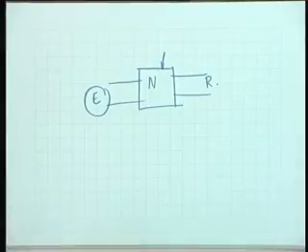You characterize each component by Ohm's law, and then write KVL or KCL to be able to solve for the network. But suppose you want a description of the network. Well, a computer aided analysis description would be that you denote how many nodes are there, and from node n to node n plus 1, what is the connection, what is the nature of the element, is it a resistance, capacitance or inductance or a diode or something else.